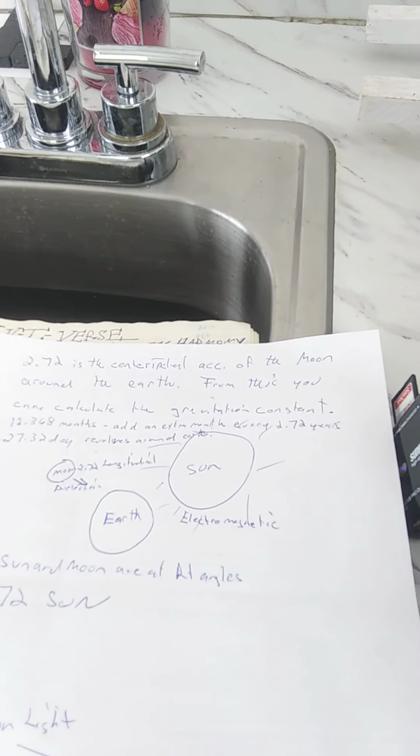So what it says here is that each Model T Ford runs using 4 coils, 1 per cylinder, housed in a box. That's the black box that features contact points for a power supply and contact points to the timer for each coil via a wiring loom and a contact terminal for a spark plug lead. The style and location of the coil boxes change throughout the years, okay? But they all do the same thing.